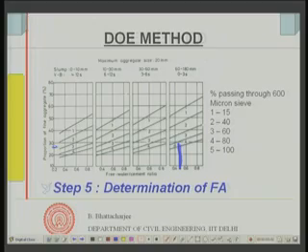Now, if I use less fines and less coarse aggregate, it will automatically mean my paste is higher, but at the moment I have already fixed my paste content. What I am trying to do is determine the ratio of coarse to fine aggregate. So, in this case this would have been something like 28, earlier case you have seen it was about 32. Since my MSA has increased, this has reduced by about 3-4%, right, for the same sand. If the sand was a coarse sand and same water content, I would have got something like about 50-55% for this kind of slump.